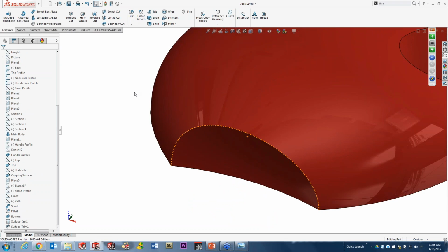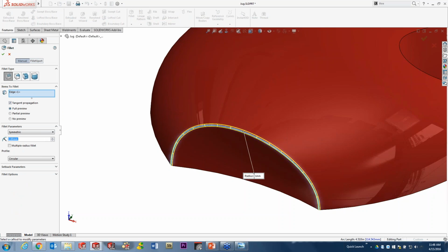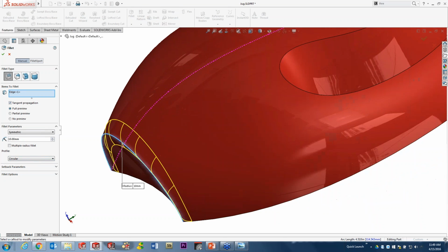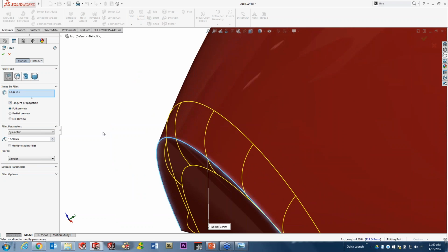And this is something that had a really extreme addition to it this time around. So by grabbing the edge, again, the most common fillet input, constant radius edge selection, we're going to start right there. Now what you'll typically see in any fillet selection is a nice preview of that. But now with our common edge constant size fillet, you can change this from a circular radius to something that is more parabolic. Now all the time a radius has been something that is just a round. If it's two perpendicular faces, we call it a quarter round, but it's like rolling a ball bearing between these two faces, and whatever that radius is would be physically round.